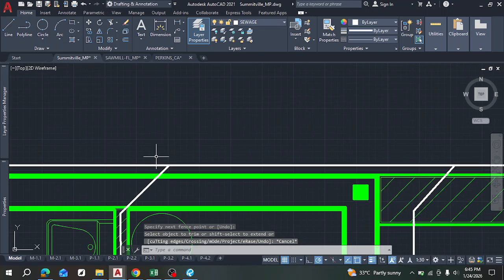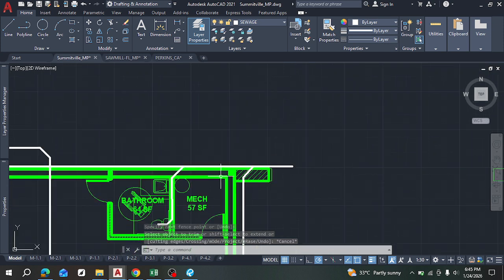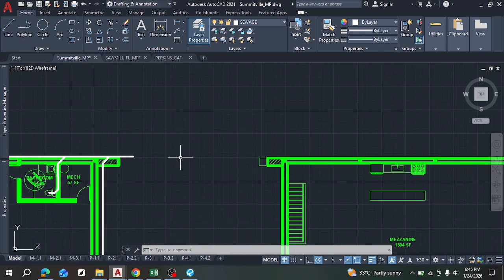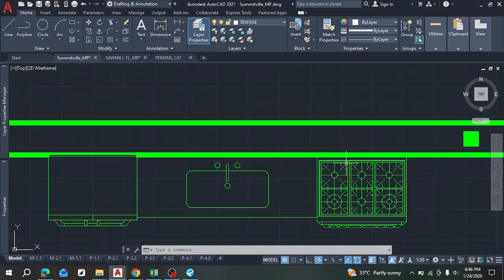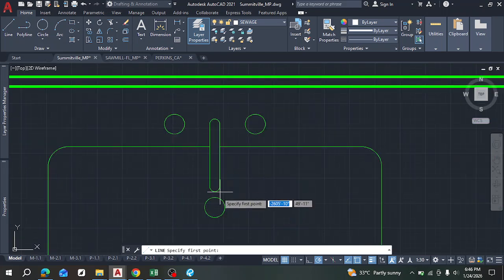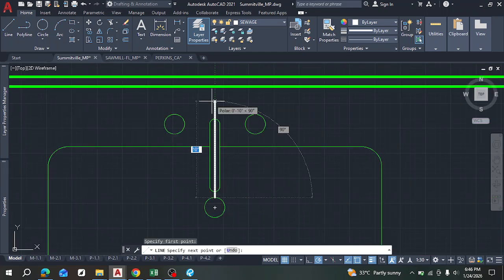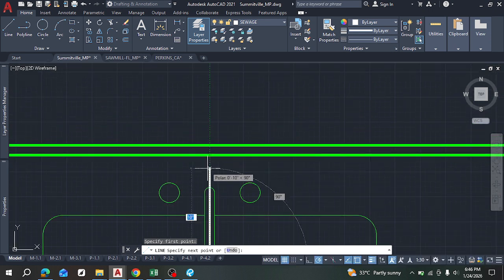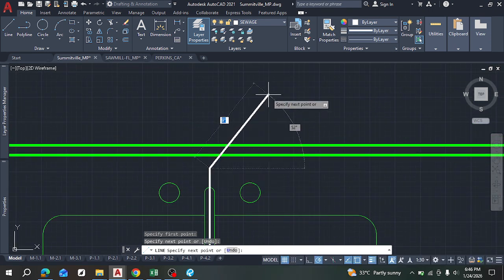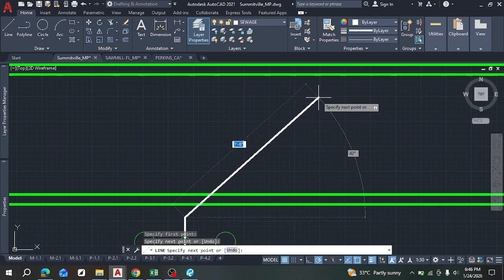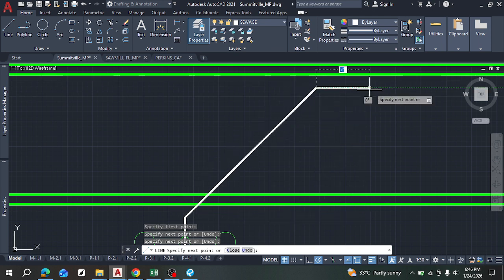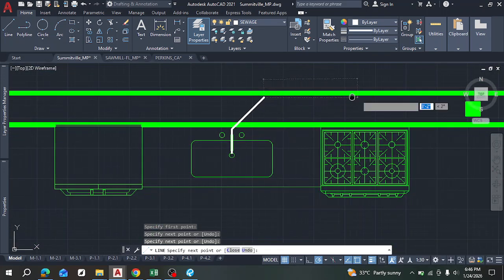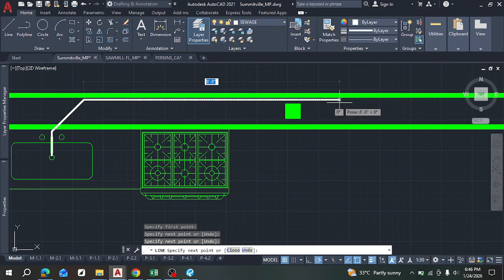Okay. What else? We also have our sink from this mezzanine floor, right? So it's just going to pass outside. If you remember, we had to deal with passing the freshwater lines right here, and a little thing I just did was to make them run on the inside, so we can avoid the issue of freezing. So then this one runs on the outside, being that they are going to be running beside each other.